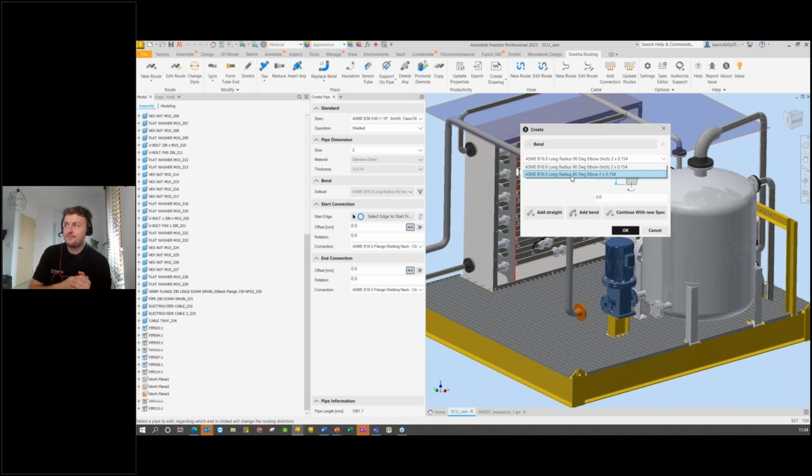Right, but you only need to add the one custom angle part, and it would then take your information every time. Say we use one system to follow 1/100, one system to follow 1/50. You'd have a custom angle drop down, and then you'd set your angle in your window there. Is that what you're saying? Yeah, correct. Right, so that seems a lot easier to set up for a start. So it would be easy to get one custom angle elbow in our drop down menu then, right?